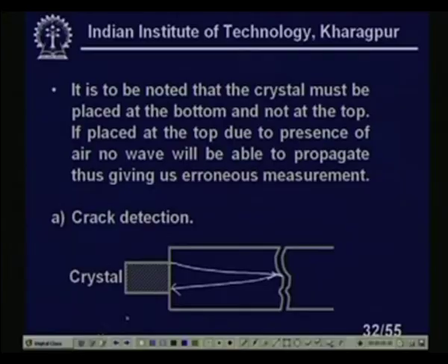I mean, we have different techniques of crack detection. We have the method of X-ray and all this, but it is very cumbersome. You know, you have to take an X-ray, it is hazardous, you have to shield the people who are working there, then you need a plate to develop all those things, but that is not necessary here in the case of ultrasonic signals if you use them for crack detection.